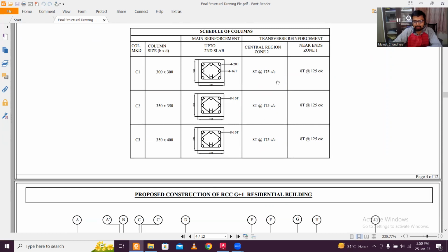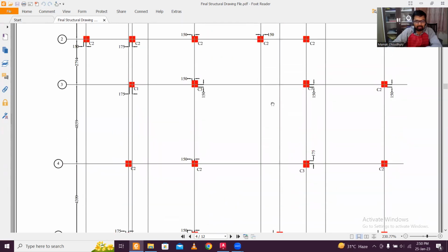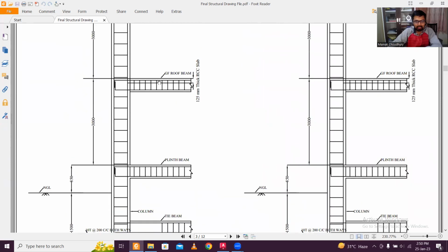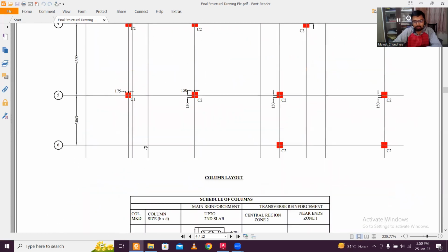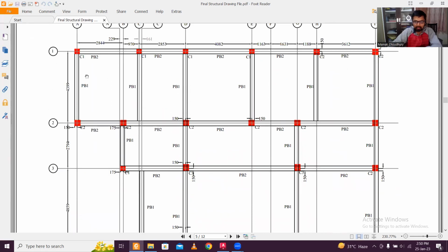In the rebar, you have these zones near the ends, and there is less reinforcement at the central region, where the tie spacing is more. So that is kind of covered. That region is actually L by 4, L being 3000, so 3000 by 4. There will be 125 spacing of the ties, and in the middle there can be more spacing, that is 175 spacing. So this is it, and that could have also been mentioned.